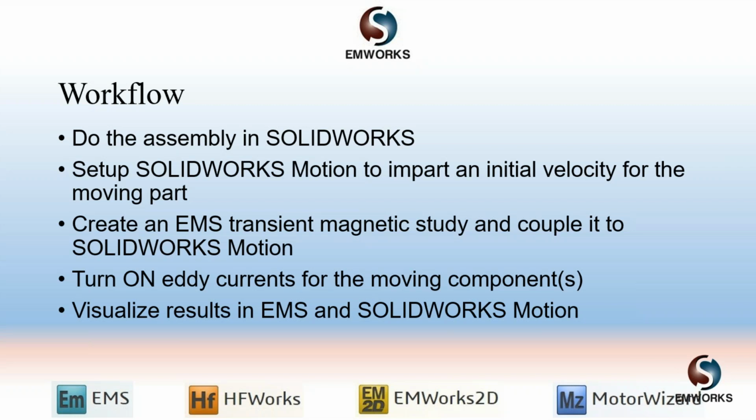Okay. Then we need to create a transient magnetic simulation and do a multiphysics coupling to SolidWorks Motion using EMS. We assign materials, then we apply the direction for the magnets, then we also tell the program to calculate the eddy currents on the moving components as well as the torque on the moving components. Finally, we run the simulation, and then we visualize the results in EMS.